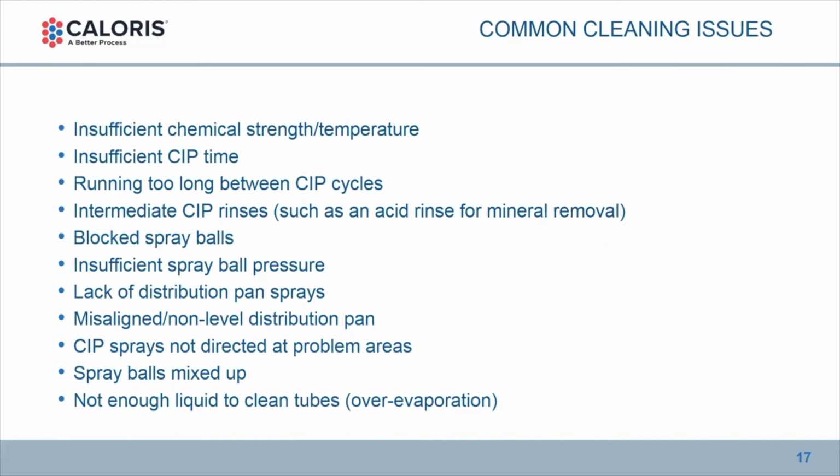Say you run 10 hours and you've started to foul out. Rather than push another 10 hours with fouling, where all you can use is delta T to hammer it home for the rest of the day, if you stop and do a good cleaning, you start with a clean evaporator for the second part of the day, and you are much more energy efficient for the remainder of that day.